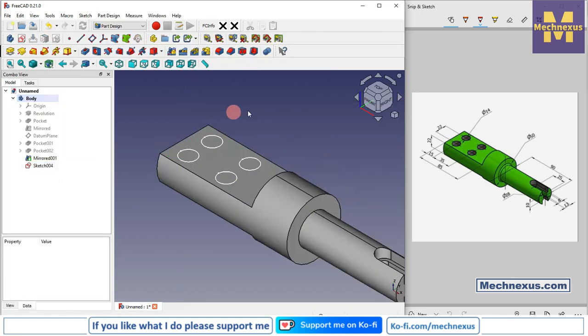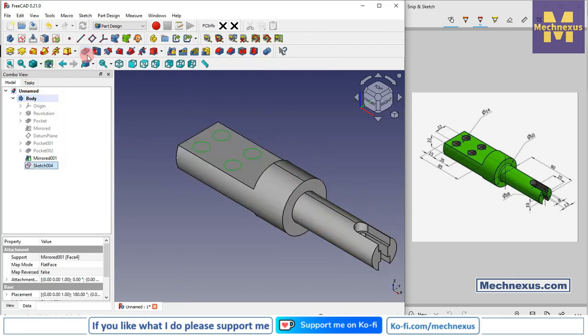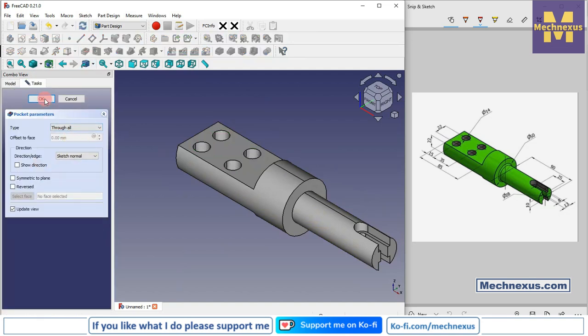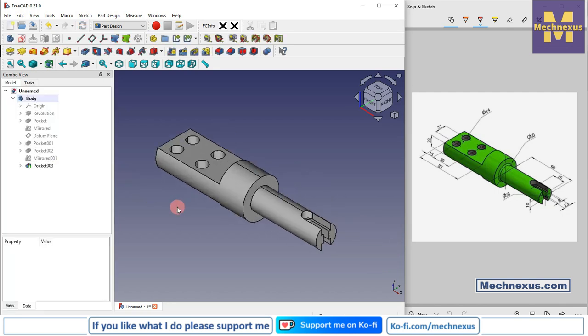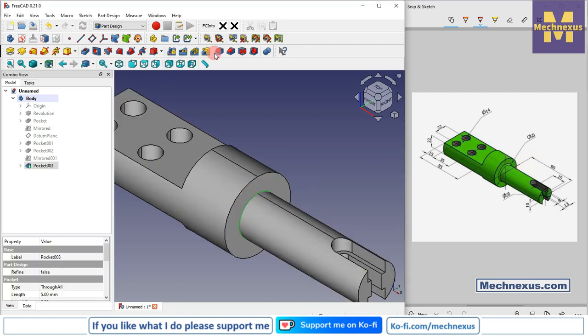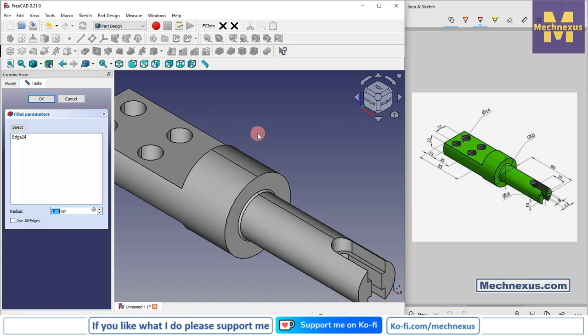And now we come out of the sketch, select the sketch, click on Extrude Cut, and from here say true all, say OK. Now here is a fillet of R3, so we will select this edge and click on the fillet and provide the fillet of R3, click on OK.